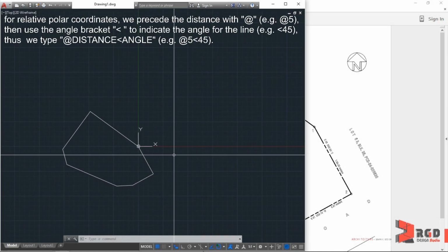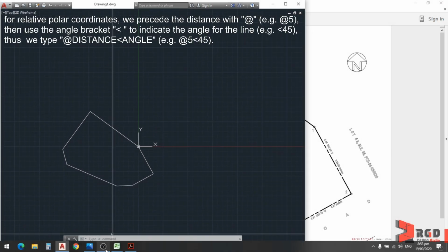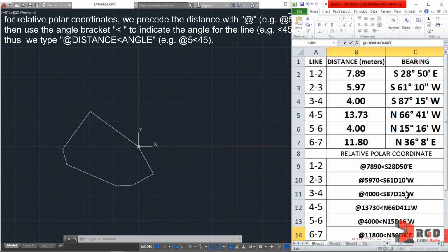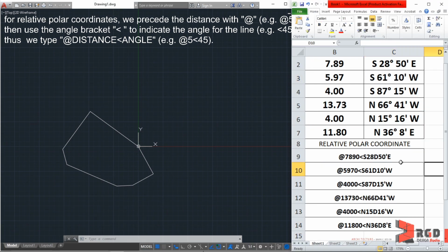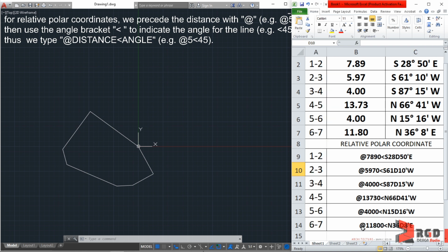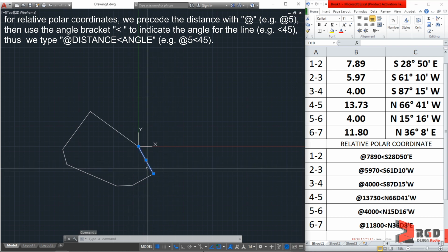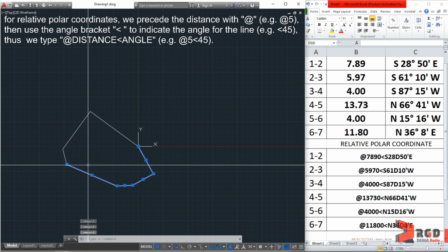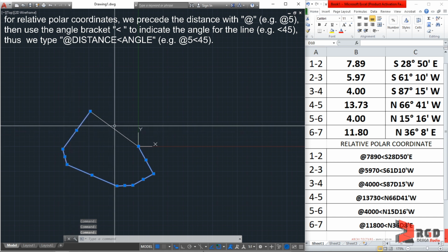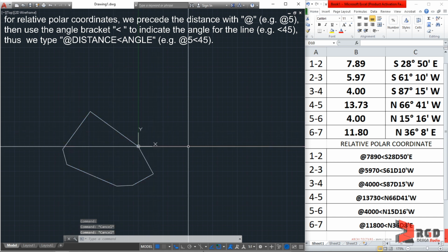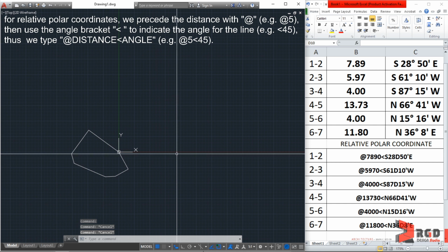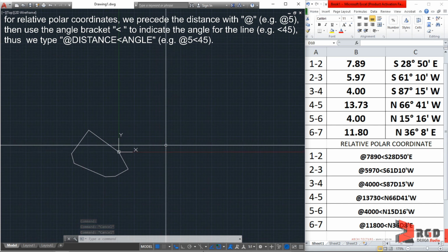Another example of creating this. Okay, so I'll bring this back and just correct this first, and there we have our input values. Now we have created our lot plan using the line command and separated this individually. So we can do this better using a more improved line command, which is the polyline.